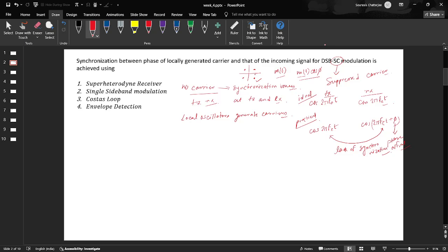In the constellation diagram, it is equivalent to this message being shifted to this, maybe something here. That is of course not a part of the standard QPSK constellation, so you will have a hard time finding what is being transmitted. That is why I am saying this is the distorted message.